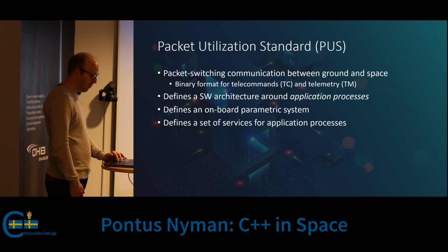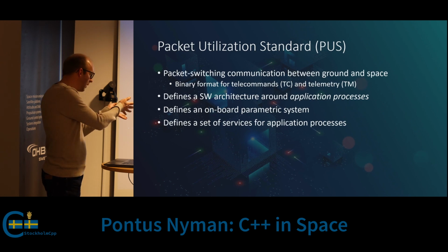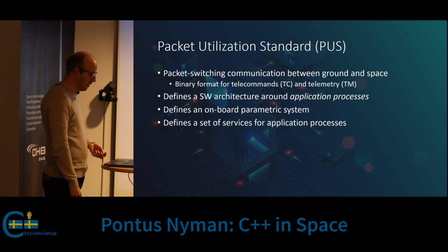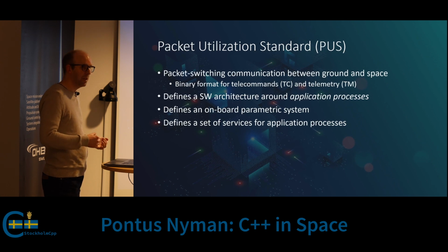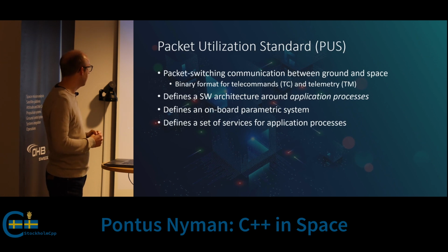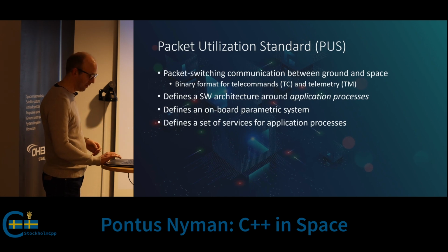So it can be like a device access service that makes it so you can access some device directly just to do some debugging or something. It defines housekeeping and event reporting services, time management, even a test service that's almost like a ping server, so you can check if everything is alive. So yeah, it defines about 20 of these services.